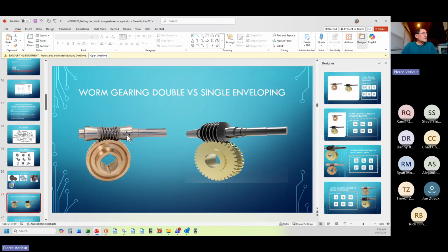This, back in the day, up until the advent of 5-axis CNC, was expensive, required special tooling, hobs. I've represented Cone Drive forever, and we used to hand lap these gears before we shipped them. You can imagine what that added to the cost. Now, with 5-axis CNC, the cost of double enveloping has come much closer to straight worm, but you get the advantages of extra teeth of contact. The efficiency goes up 10, 15 points.